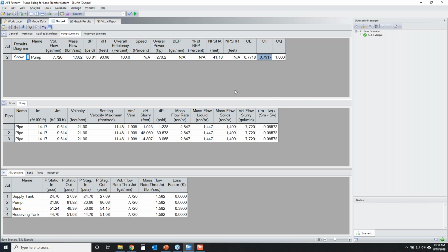And the amount of pressure gain across your pump is going to decrease by 21%. So you want to make sure that when you're sizing your pump, this is your operating point for flow and head. You have to make sure that your pump can actually accommodate 21% extra head in order to appropriately pump at these operating conditions. So this is your derating factor, and that's what you need to account for in order to properly size your pump.